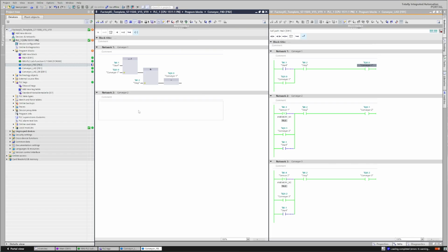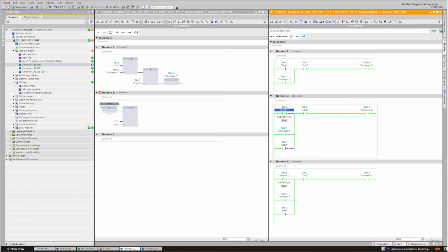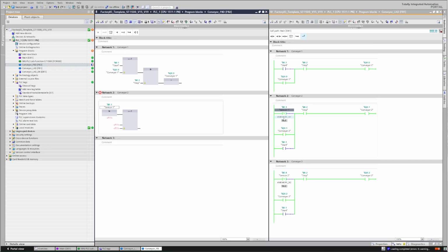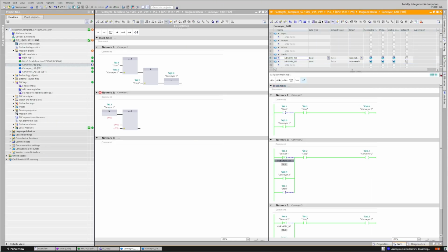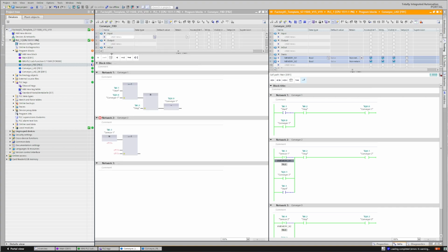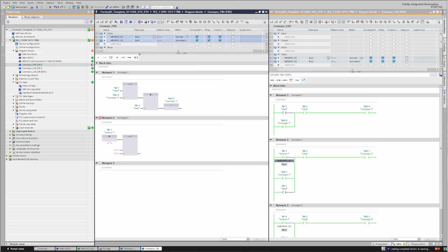Conveyor 2. Here we can make an OR. Yeah, we have OR for 3 conditions, right? We make OR. We say if it is a N trigger, we say N. If it's a negative edge, and here we use the sensor 1. And this one we can also copy from here under the static.